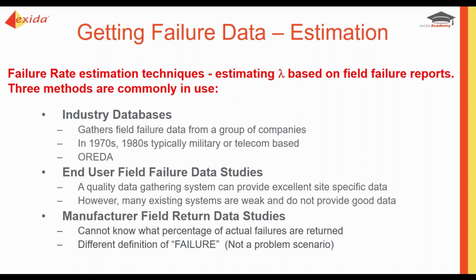The next way of estimating failure rates is end-user field failure data studies. Once again, there are pros and cons. If you have a high-quality data gathering system, this is awesome information. This is site-specific data. This is a gold mine for you end users. Once again, don't just leave it in your data collection system. Actually analyze it. Look at the as found conditions. Look at how the failure happened and trace it back. You can really eliminate a lot of your systematic issues that way.